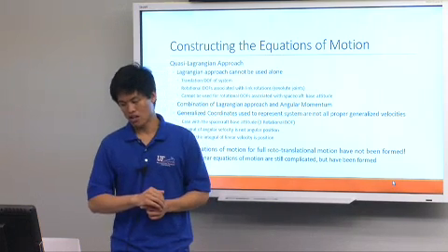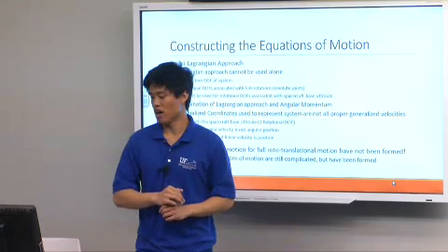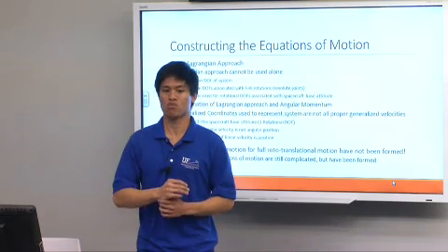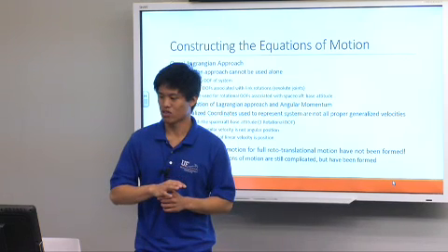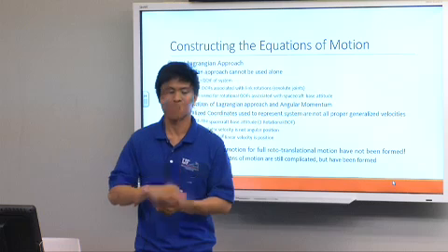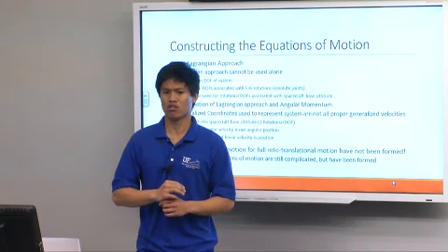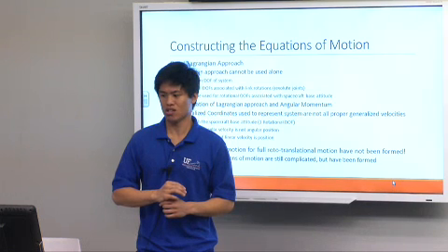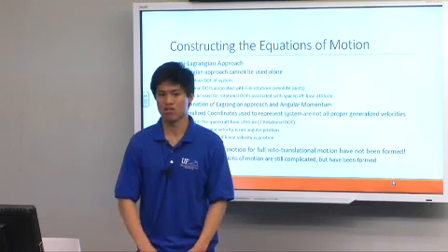But for the spacecraft base attitude, we can't use those generalized coordinates. Did you go over kinematics for the, okay. That's because when you integrate angular velocity, you do not get the angles. It depends on how you represent it, whether you use Euler angles or quaternions or whatever.